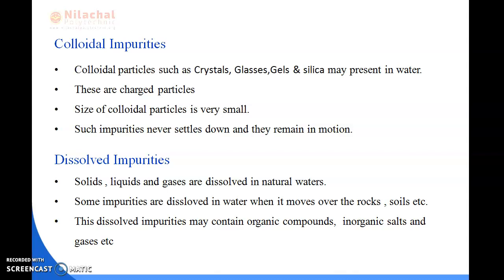Acid or neutral materials like silica, glass and most of the organic particles acquire negative charge in the water, and those that carry positive charge are metallic oxides, such as aluminum oxide. When these positive and negative charges collide with each other, they may cause the particles to repel or attract each other. Due to this repelling action, the colloidal particles do not settle down, they always remain in motion.